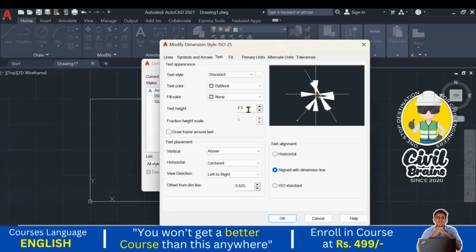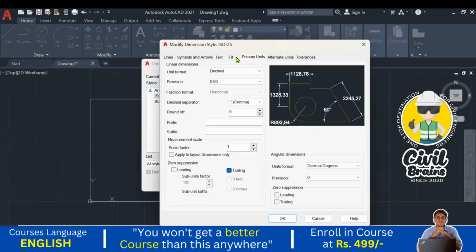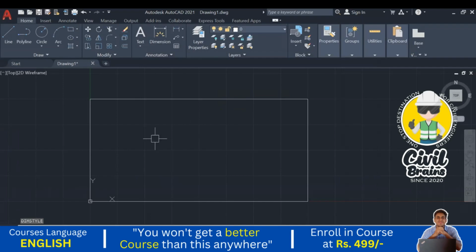Next, text. I consider the text height as 200 so it will be visible properly. And this will be centered, horizontal, according to that. And fit, primary units 0.0 and all those things. Press OK and close, so that the dimensions will come correct.